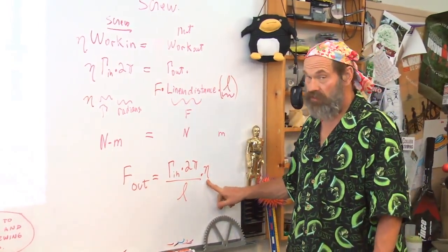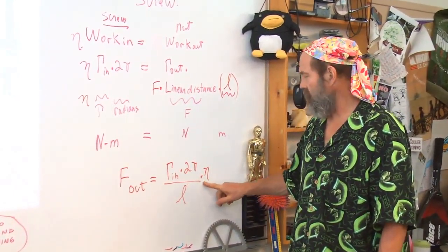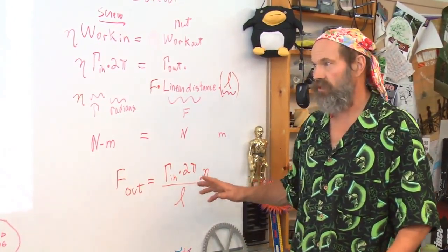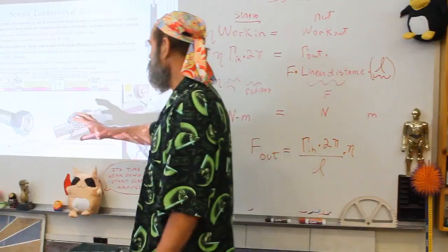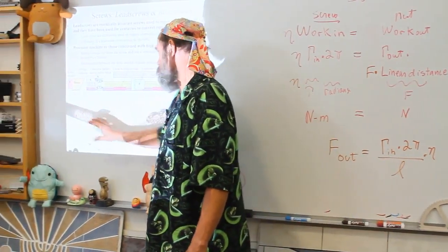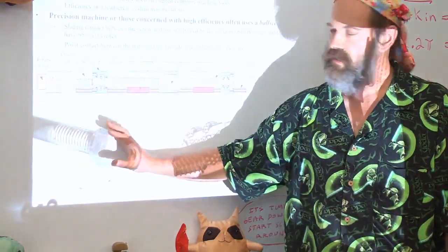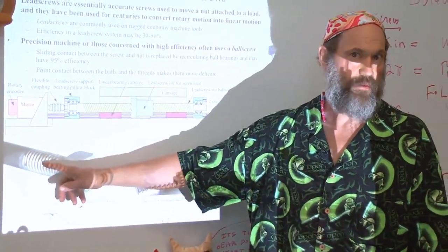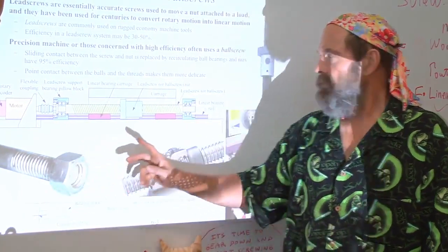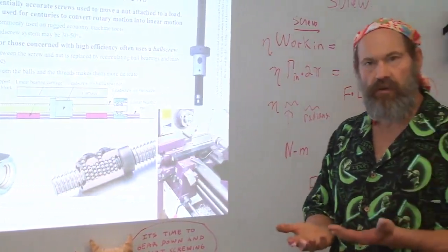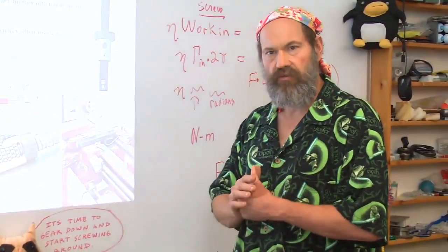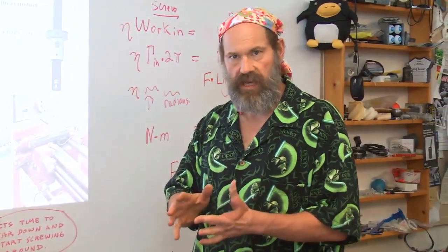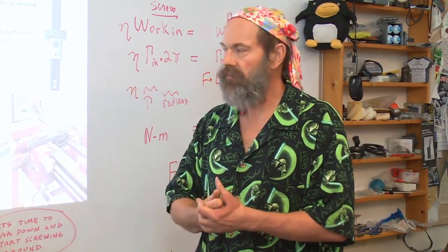And okay, efficiency, good efficiency. This is where the limits become apparent in real systems. If you want to apply a torque to a bolt and have a huge force in the nut, that means you want to have a low coefficient of friction between the threads, which means the threads have to be lubricated. If you just take a cruddy old thread with a rusty old nut, you're not going to generate that much force. Lubricate it, and oh, that works really good.